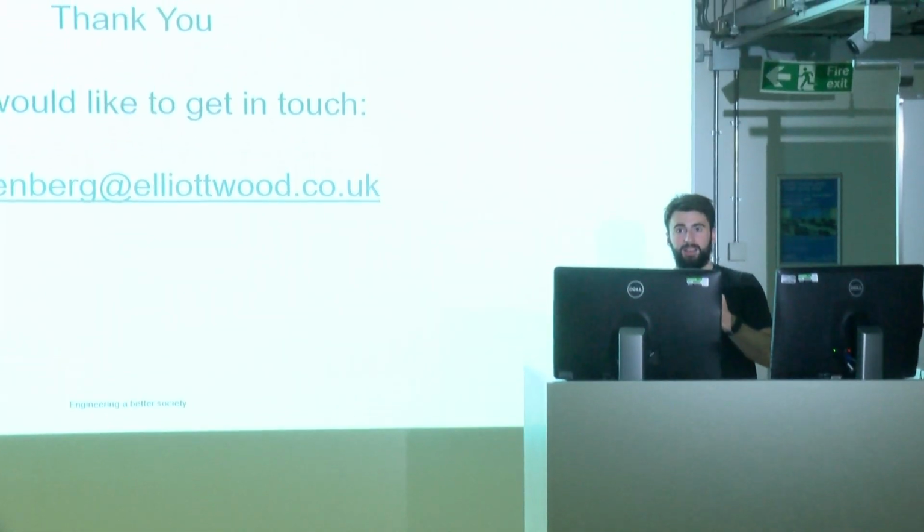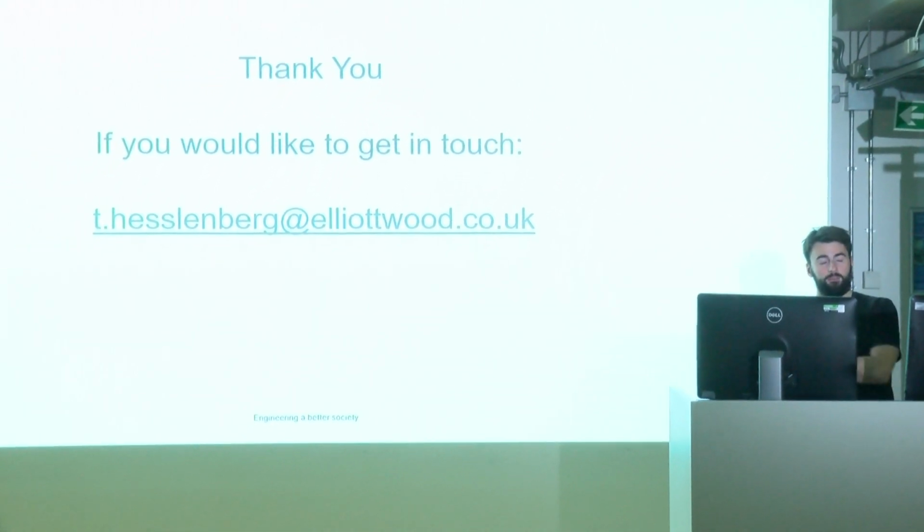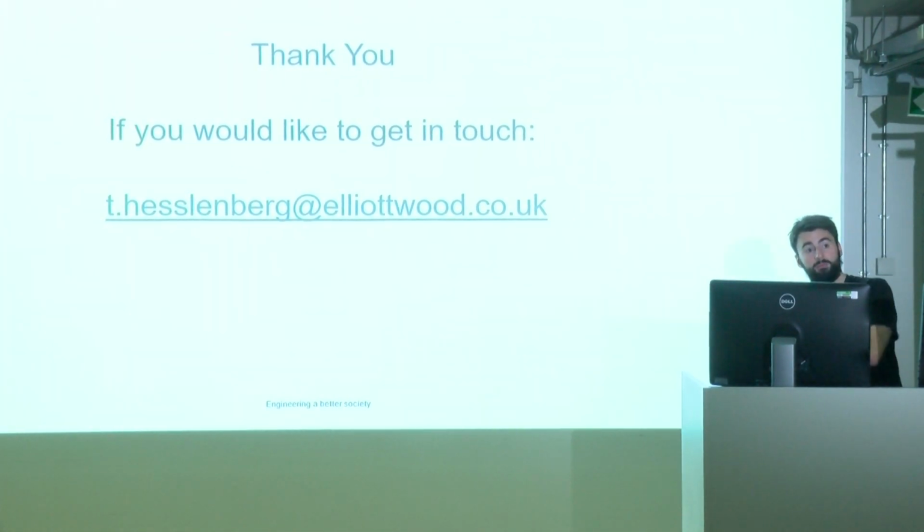We're doing a lot of projects at the moment where the structure is governed by the facade's deflection limits, how much the beams can deflect before it becomes a problem for the cladding. Those deflection limits make our beam sizes and column sizes greater, because we can't allow them to deflect as much.